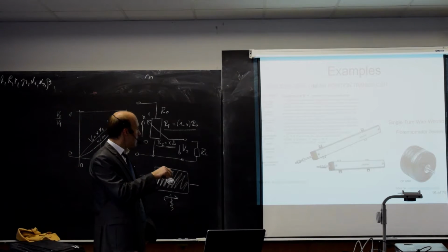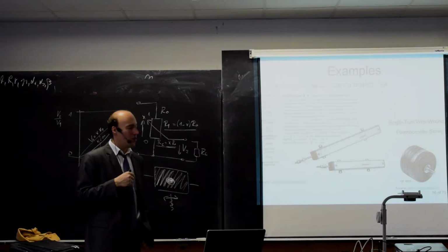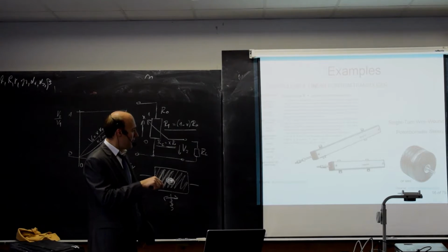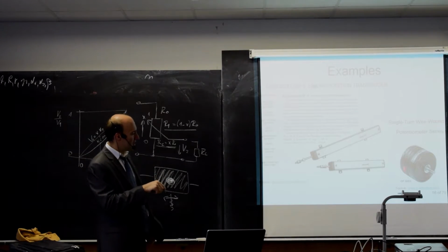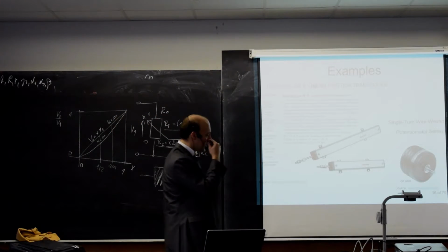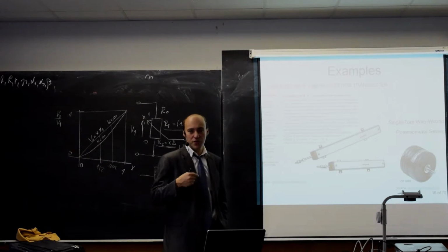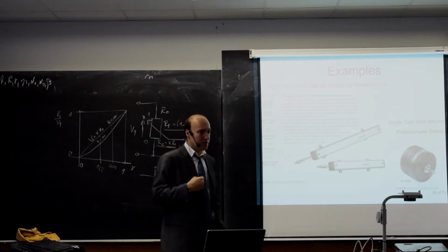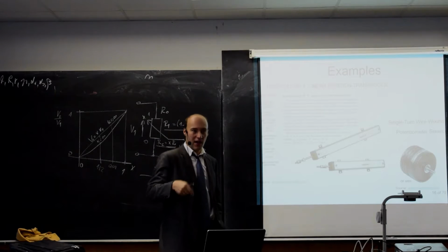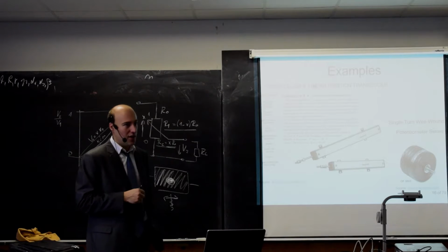So those are linear sensors for linear position. But the same thing will work also if you make the track circular, and you can have variable resistors, sensors that are good for angular motion. Of course, you can transfer between linear motion and angular motion with a gearbox, for example. But if you directly know that you will use an angular sensor in applications for angular motion, then you don't need any gearbox at all.